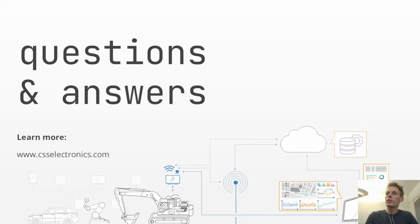Then there is a question on how we can send vehicle-specific requests using a CL2000, which is one of our other data loggers, to get expected responses without recording all of the data. And for this purpose, you can set up CAN ID filters on the CL2000. They are more basic than on the CANedge, but you can still do it to some extent.